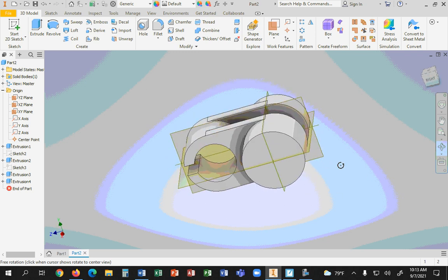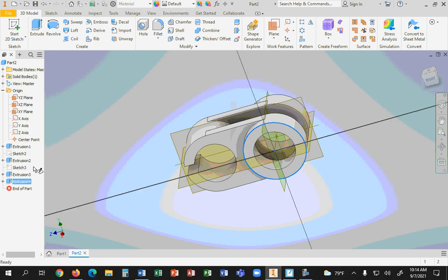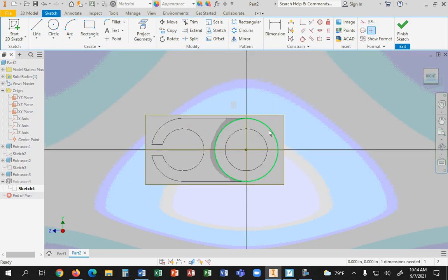So in your case, that's what you would do, because I have a feeling that's what you did, right? You added on the extra hole, but you drew it without locking it to the outer shape. But you can edit the sketch for that. Like in my case, let's say I screwed up and I didn't want it to be the same diameter. I can edit that sketch and you can drag it away. I didn't actually lock that one. Let me lock it first so you can see.